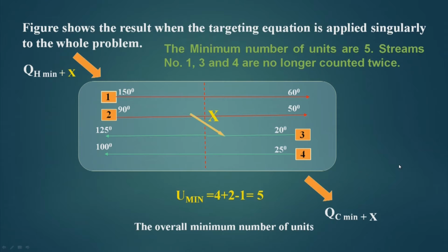So, that much area will increase in the heater and cooler. So, there is a penalty which has to be paid if we pass heat through the pinch, and then the design is no more MER. So, if I pass it through the pinch, I will call it a non-MER design.